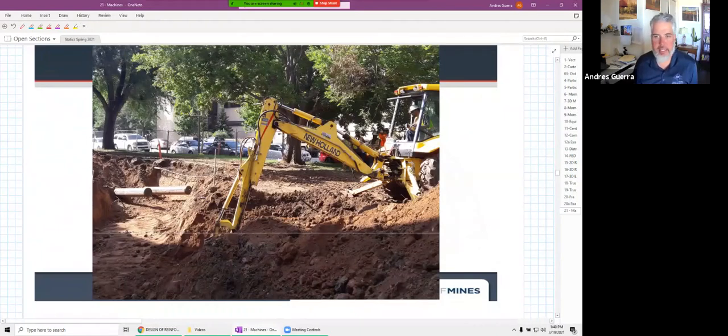So like this backhoe that I've shown you a picture of before, this is a really great example of a machine, but it's all just composed of multi-force and two-force objects. This right here has 1, 2, 3 locations of forces. It's a multi-force. The hydraulic cylinders, only 2 locations. So it's a two-force.